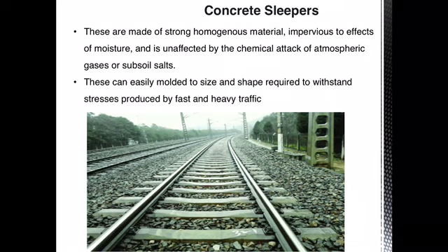Okay, and then it will be impervious to the effect of moisture, and it is unaffected by any chemical attack. There is no corrosion, no decay, nothing. Atmospheric gases cannot decay your concrete sleepers, and subsoil salts will not affect the functioning of the sleepers in any way. The manufacturing is also easy, because concrete can be easily molded to the required size and shape, and it also withstands high stresses produced by fast and heavy traffic.